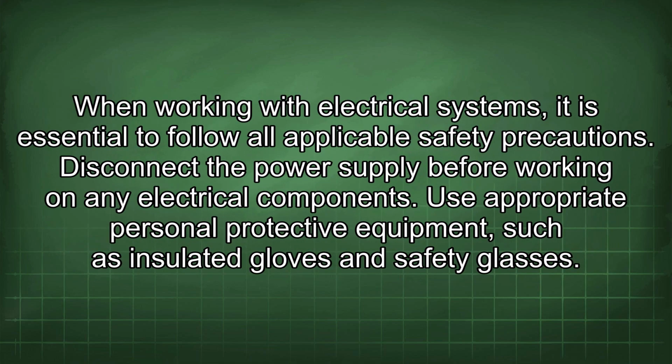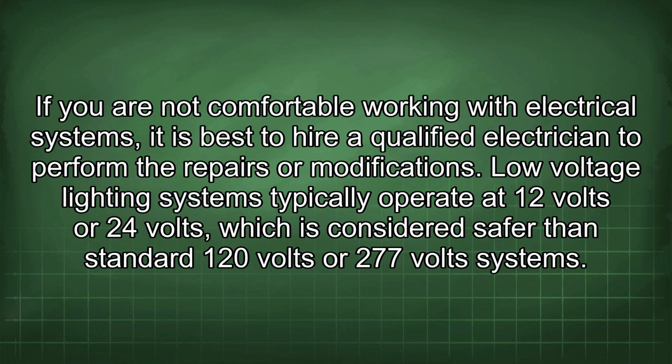When working with electrical systems, it is essential to follow all applicable safety precautions. Disconnect the power supply before working on any electrical components. Use appropriate personal protective equipment, such as insulated gloves and safety glasses. If you are not comfortable working with electrical systems, it is best to hire a qualified electrician to perform the repairs or modifications. Low-voltage lighting systems typically operate at 12 volts or 24 volts, which is considered safer than standard